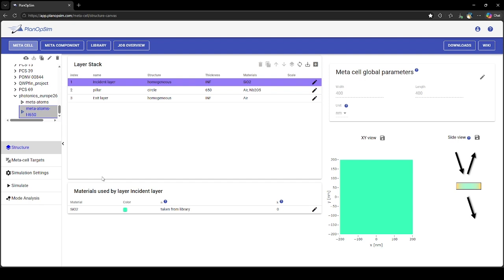Because these nanostructures are sub-wavelength in size, it is important that we simulate them using a full solution of Maxwell's equations. In our case, we use the RCWA solver because it's proven to give accurate solutions to Maxwell equations, and at the same time be very performant in terms of time and memory efficiency for these type of structures. But let's start at the basics by defining our structure. RCWA is built up as a periodic simulation with different geometric layered constraints.